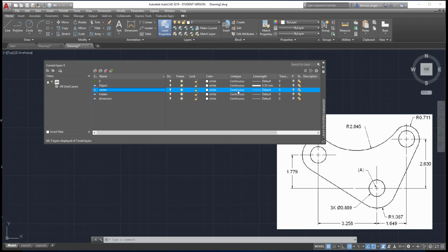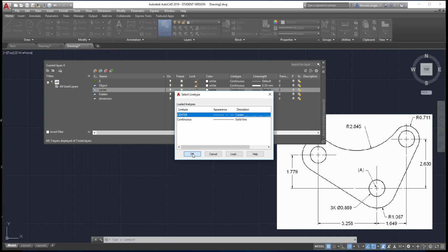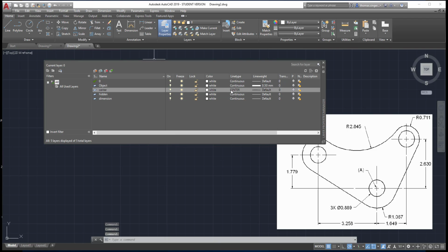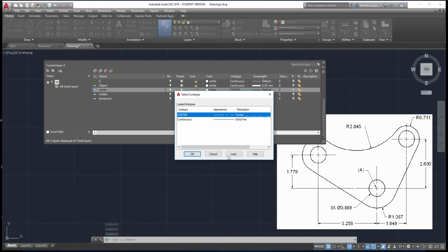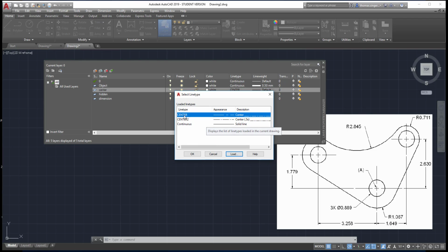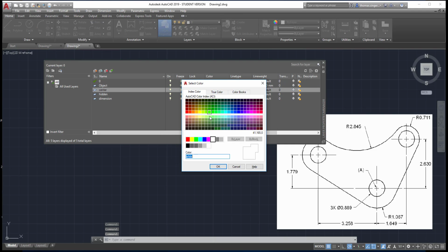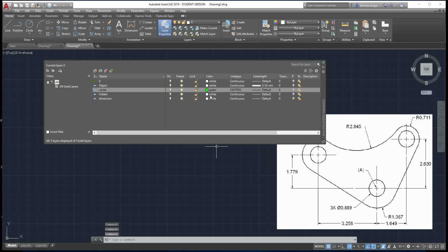Center, we're going to have to set up continuous line types. We're going to have to go to center line types and select the center line. And this one may be too big, so we might actually have to go and not just do center, but choose center 2, which is half the scale. There is a command called line type scale that we can use to scale our center lines, but if you know that it's going to be a smaller drawing, in this case it is, it's only about 6 inches in size, a little bit bigger than 6. Again, center 2 may work better.